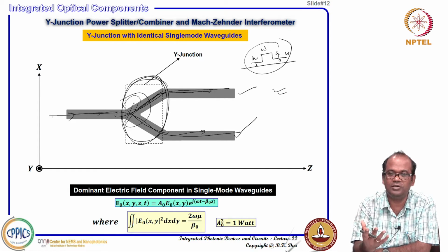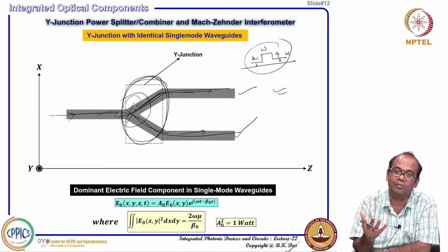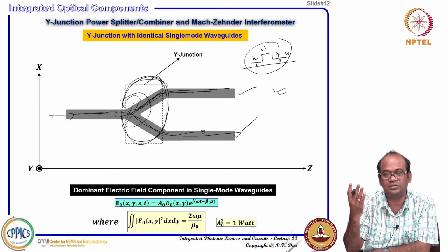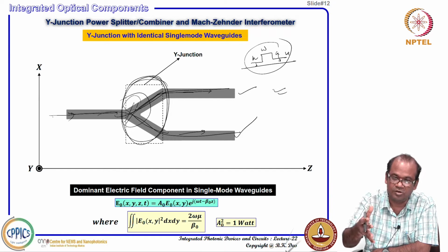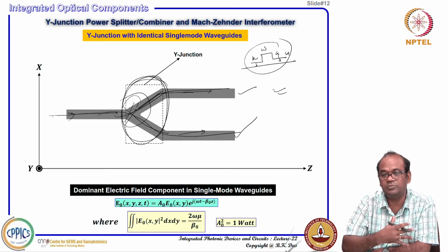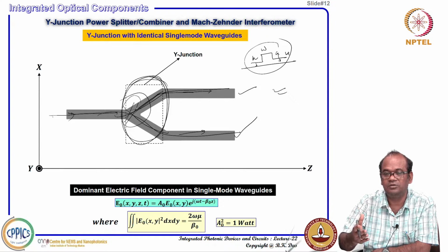When the orthogonality condition breaks, that means you have to think about coupled mode theory. That particular mode will be disturbed, and there is a possibility of energy transfer to all other existing modes, including radiating modes, as long as mode matching and phase matching happen, which are the two conditions required for coupling.